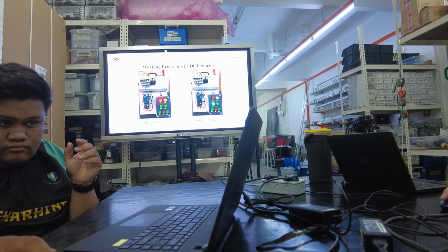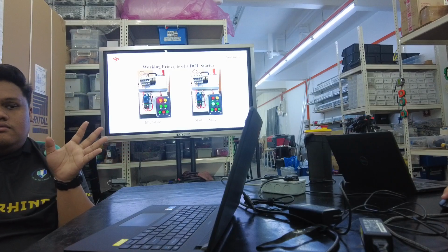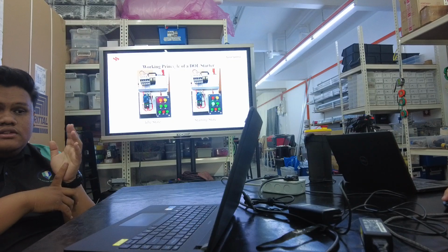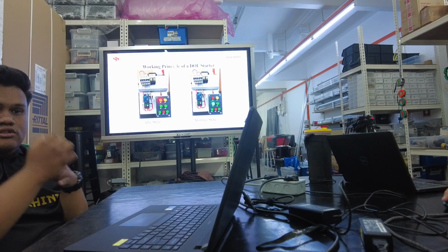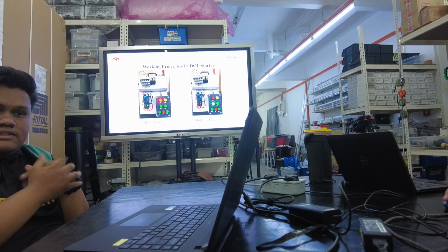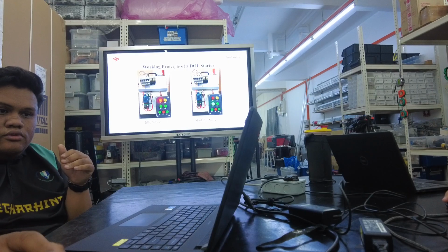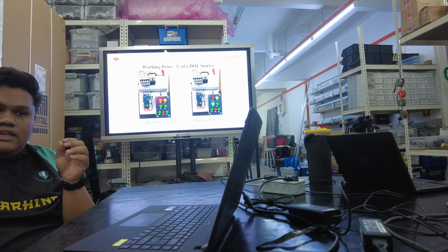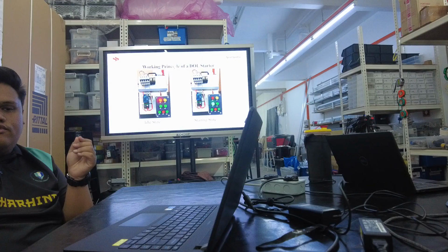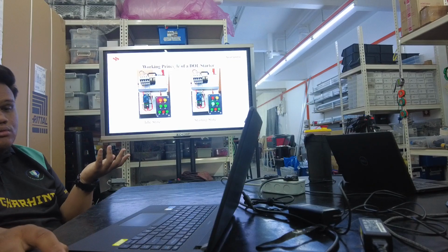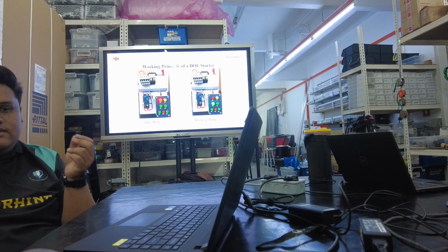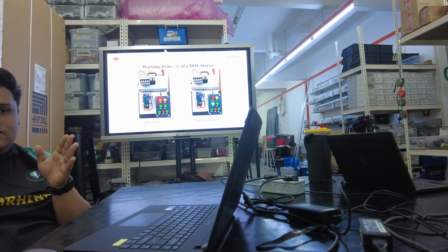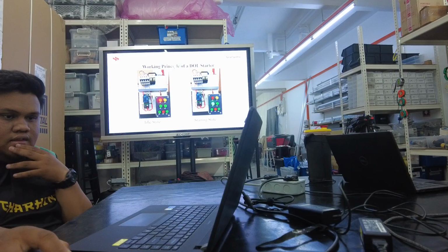And then the starting: when we start the motor, or press the start button, the control circuit is completed, the contactor coil becomes energized, and the contactor pulls in, so the main power contacts close. The motor is connected directly to L1, L2 and L3, which means full line voltage. So what happens to the motor? The motor draws a high starting current, and the starting torque is high. The motor begins to accelerate from 0 speed.